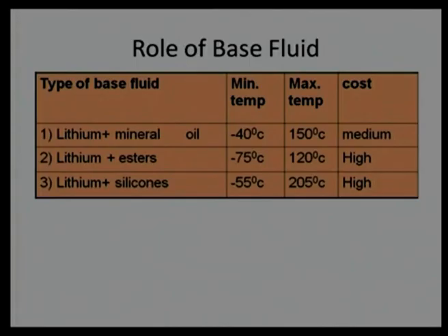This slide shows the importance of mineral oils, silicone oils or synthetic oils. What we talked about in the previous slide was the thickener, and how using different thickeners the performance will change. But when we select the thickener, particularly lithium base, aluminum based or polyurea base, we need to think about what the carrier fluid should be, or what will be the base fluid which is used with the grease.